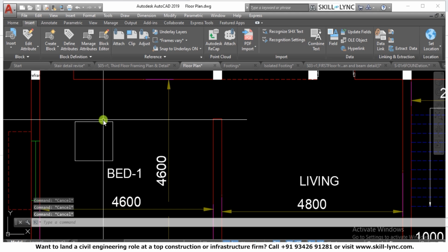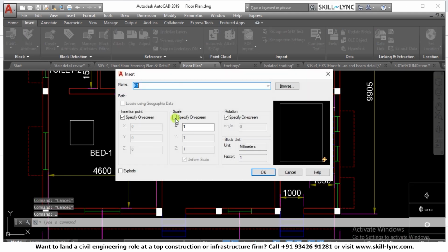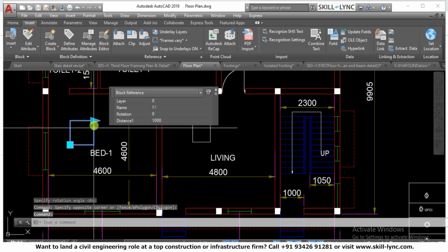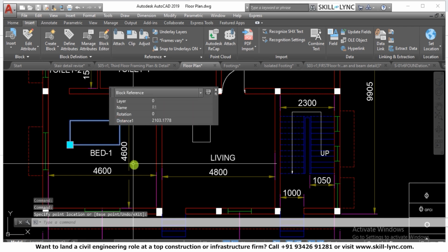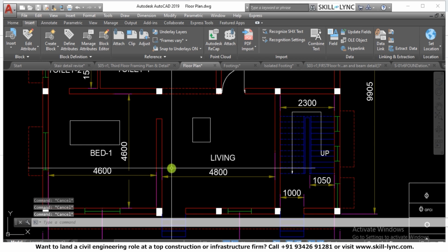Now what happens with this change? If I insert another block over here, is this change reflected in the other block also? The answer is no. When we have a dynamic parameter, the individual entity changes. It is not that all the objects of the same block will change. So this is the stretch parameter and action in the dynamic block. The first option we did was incorrect, and sometimes we go wrong by selecting the wrong parameter. Now this is the right way of doing the stretch.